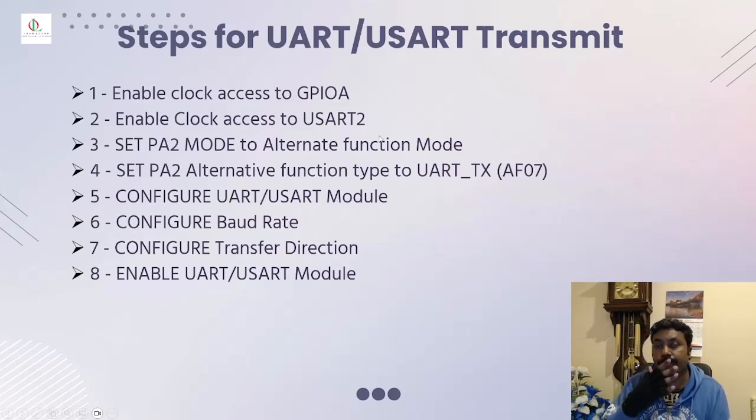If you cast your mind back to that LED blinking project, you would understand you have to enable that clock first, so that the microcontroller knows which port that input or output is coming from. So that is why the USART needs clock access, to alert the microcontroller. So that's a must. And every port and every peripheral is associated with internal registers, and that's how you can write a program. You have to write a program to set, enable or configure those registers.